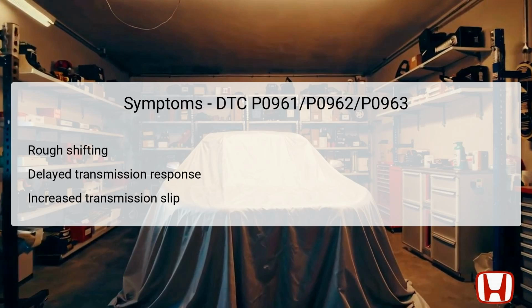Another alarming symptom could be an increase in transmission slip, where the engine revs higher without a corresponding increase in vehicle speed. This slip not only affects performance, but can also lead to further mechanical issues if not addressed promptly. Recognizing these symptoms early on allows for quicker troubleshooting and minimizes potential damage to the transmission system. Awareness of these indicators is crucial for vehicle owners and technicians alike.